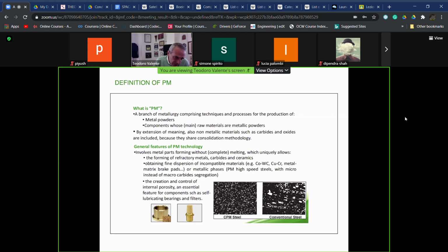It's also very interesting, perhaps you can appreciate this picture, the possibility to strictly control the consolidation phase, in the sense that starting from powders, we could stop the consolidation due to solid state diffusion when we want, having a controlled, also high, residual porosity inside the material itself.